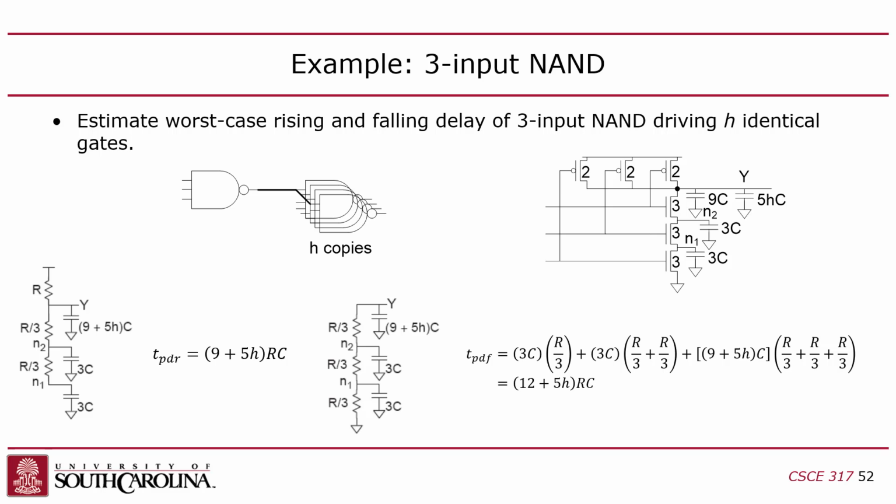you see this R value in the pull-up? I was assuming only one of those pull-ups was on, because there's only one R value here. You see that? There's one R, so I'm assuming only one of these has to pull up, because if any input is 0, then the NAND gate is going to give you a 1, right?